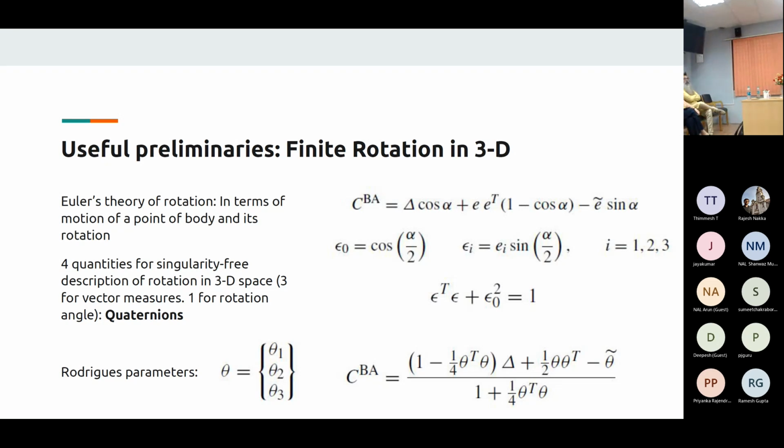This last expression is usually used when you are trying to extract back the 3D rotations. Here theta is actually the twist, and the curvatures are along the second and third axis. This will be useful when you are finally done with the cross-section analysis and you also do the 1D nonlinear analysis.